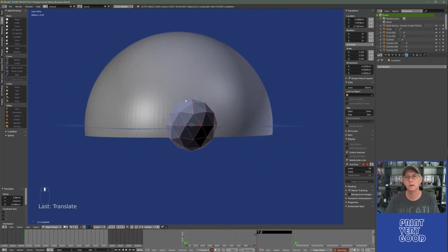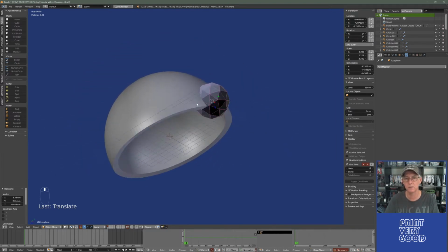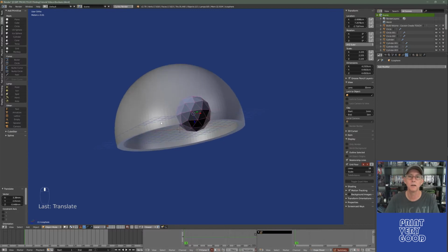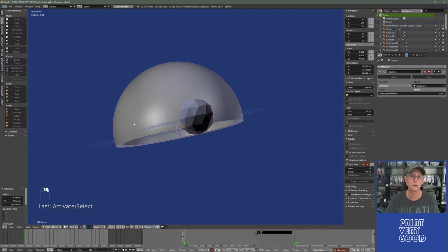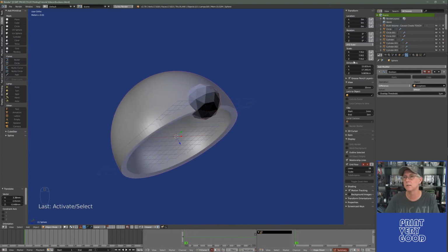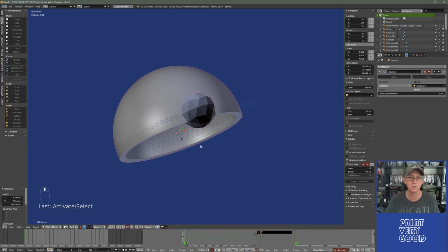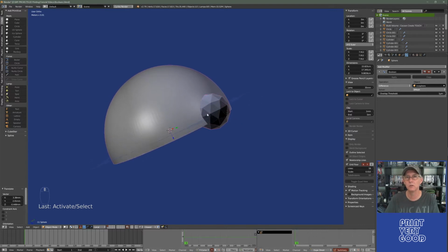And that's caused by where the vertices are lining up in relation to each other. So how to fix this problem is that you'll find that this is caused by the scale of your object. If I click on it, select it, you see here the scale is set to 7.92. So I created the sphere and scaled it up. Now when you're running a Boolean operation, you want to make sure that your scale is at 1.